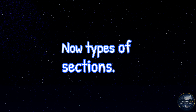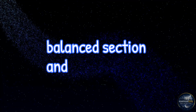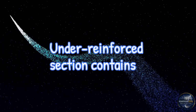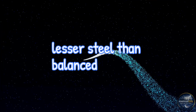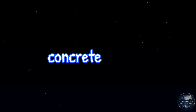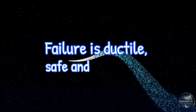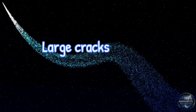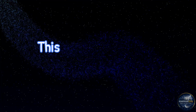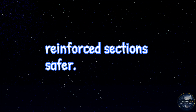Now types of sections: under reinforced section, balanced section, and over reinforced section. Under reinforced section contains lesser steel than balanced section. Steel reaches yield stress first before concrete crushes. Failure is ductile, safe, and preferred. Large cracks and deflection develop before collapse. This warning before failure makes under reinforced sections safer.